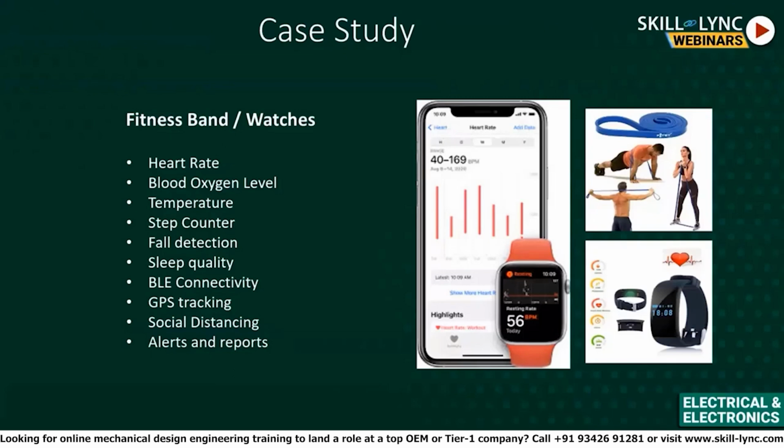So we'll be having a good amount of data, and the sensor will also have some features where the sensor gives you an alert that the data is ready. That is nothing but your data ready signal. We'll be sending a start signal to the sensor, and the sensor will start reading. The sensor will store some amount of value, and when the sensor says that yes, I have stored it and my data is ready, the sensor will send you back the signal, not the data. It will signal your controller or your processor that yes, data is ready, and you can read it from the sensor. So this is how we can read a temperature sensor.